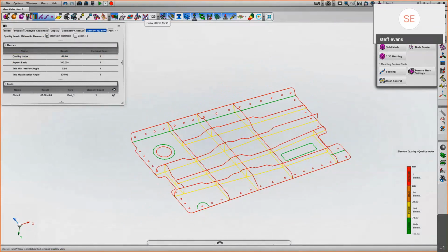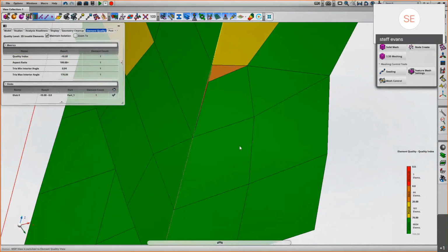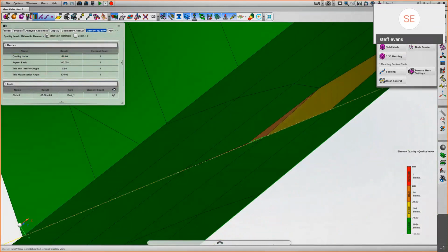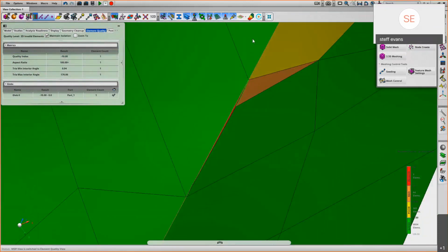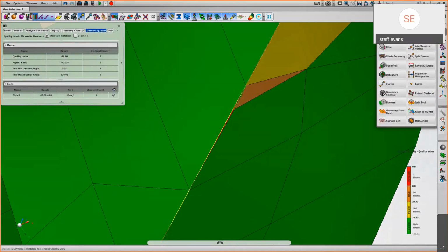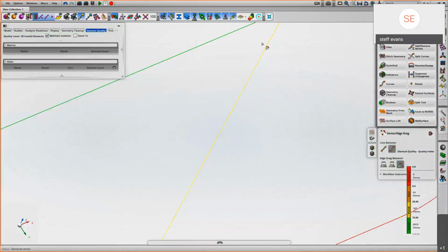Okay, we can use what we call the Grow 2D 3D Mesh tool. So this grows the mesh around the failed element. Okay, and then we can start to dig into the geometry and understand any particular problems that we've got. So it'd been very difficult to find this edge if we didn't have mesh in the model. So if we put the vertices on, we can see we've got this cut. We're just going to drag the vertex back to center.